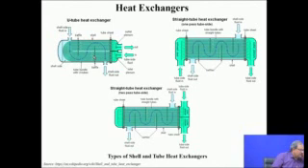So when it travels, it comes in contact with the shell side fluid, exchanges heat, and you are providing sufficient length of the tube to ensure that the outlet temperature is significantly higher than the inlet temperature, and you have a substantial transfer of the energy contained in the shell side fluid at the inlet, which is transferred to the tube side fluid. So the sensible heat increase of the tube side fluid must be equal to the sensible heat decrease of the shell side fluid.